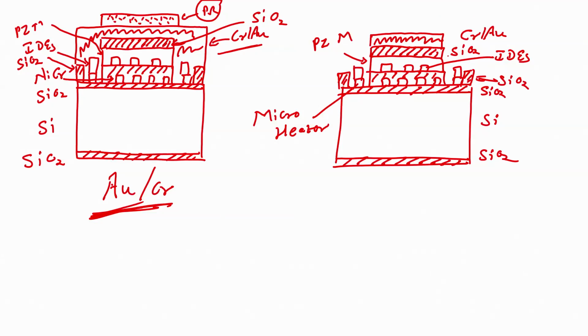Now, this is just a schematic to show it to you, right. You can also have photoresist in this particular fashion, so that your pads below the photoresist will not get etched. This should not get etched. This one and this one are directly exposed, and they are also interdigital electrodes made up of chrome gold. So, chrome gold can get etched if this is not protected with the help of photoresist.